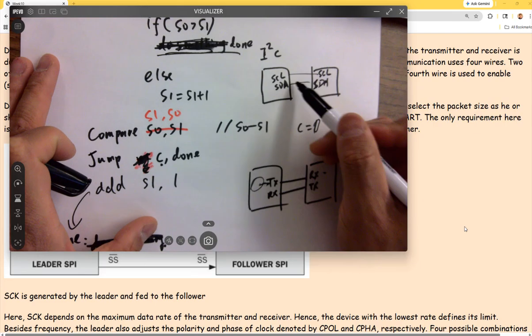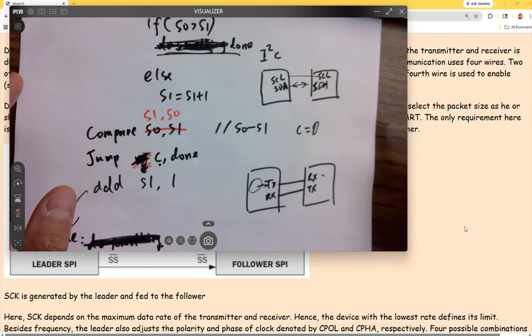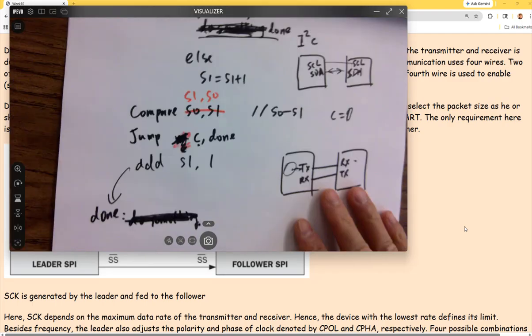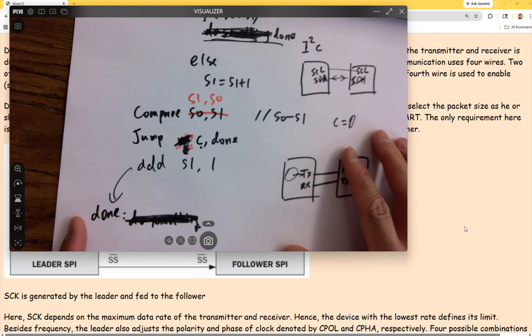It doesn't matter which direction, it's bidirectional for just one line, right? Just one line. So a lot of times it's also called a one-liner communication port. It's taking a lot fewer pin resources compared to the SPI port, right?